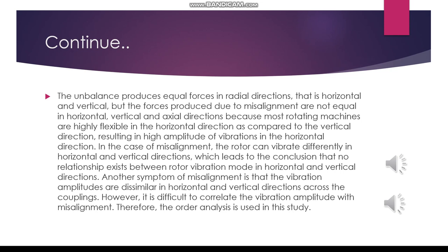Last slide for explaining the data analysis and fault diagnosis on shaft. The unbalance produces equal force in the radial direction, that is horizontal and vertical, but the forces produced due to misalignment are not equal in horizontal, vertical, and axial direction, because most rotating machines are highly flexible in the horizontal direction as compared to the vertical direction, resulting in high amplitude of vibration in the horizontal direction.